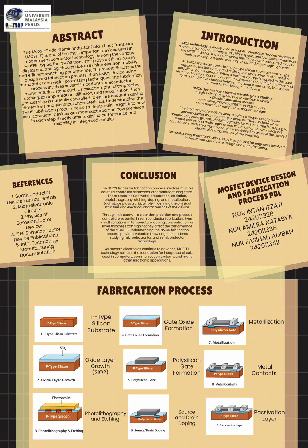When a voltage is applied to the gate terminal, electrons accumulate and form a conductive channel between the source and drain. Some advantages of NMOS devices include high switching speed, simple fabrication process, high integration capability for VLSI circuits, and lower power consumption. Next, I will pass the presentation to Mira, who will explain the fabrication process.